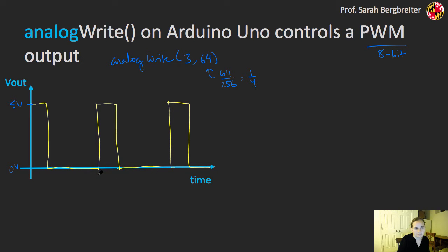Arduino, but typically a period on this would be something on the order of 2 milliseconds, for example. So if this was 0, 2 milliseconds, 4 milliseconds as an example. But this is clearly not an analog voltage that we'd expect to get out of a digital to analog converter. This is a pulse width modulated digital signal. So how do we actually get an analog voltage out of this?